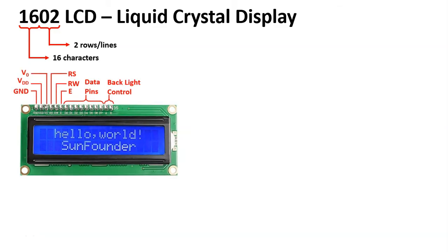Now here you can see all the pins associated or connections associated with this LCD. We start with ground, which connects to the ground of the Arduino, the VDD, which basically takes the 5 volts from an Arduino or other microcontroller. V0, it's used for LED contrast, also the text against the backlight, and we'll see that contrast in more detail later.